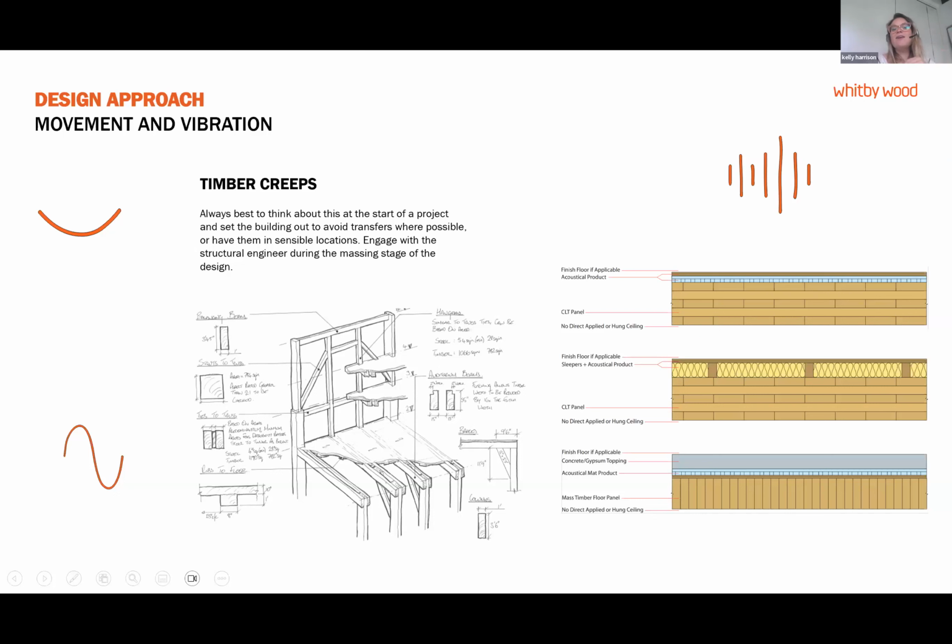So quite early on, we have to think a bit more about deflection than when we're designing a steel building, because timber creeps as well as just deflecting normally. And so you have to really look to try and limit large deflections, particularly cumulative deflections. So if you have secondary beams on primary beams with transfers, it's horrible. It's a nightmare. You end up with spreadsheet upon spreadsheet trying to figure out what's going to deflect when, at what part time during the construction and during the life of the building.